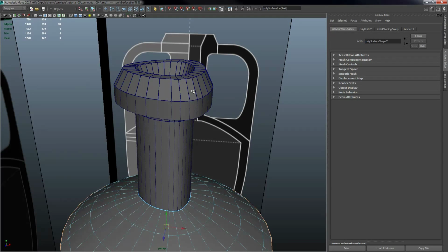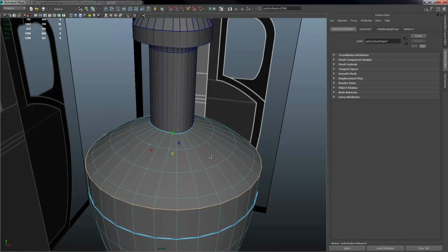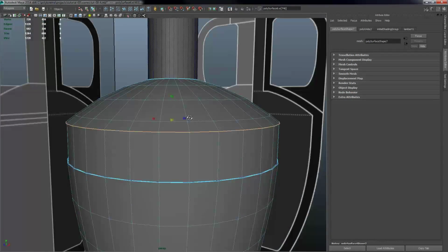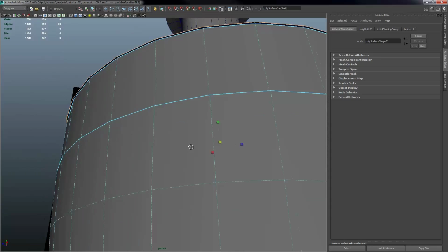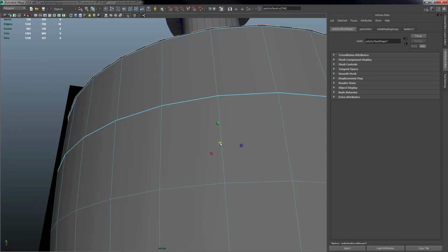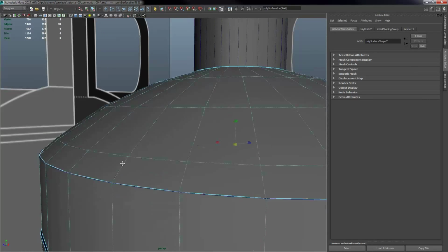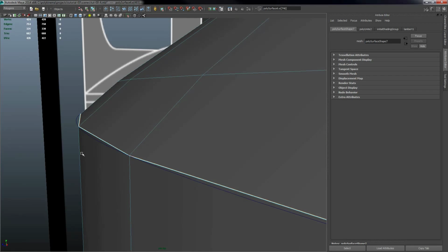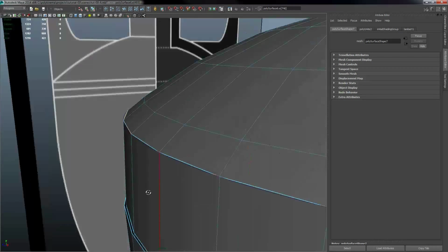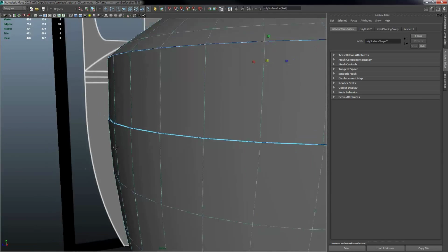I just hit the move tool and bring the scale tool back up again to reset it to its default spot. I can bring all those edges in so they line up pretty closely because I don't want to shift that cylinder out too much. That looks pretty good. I'll do the same with this one down here.